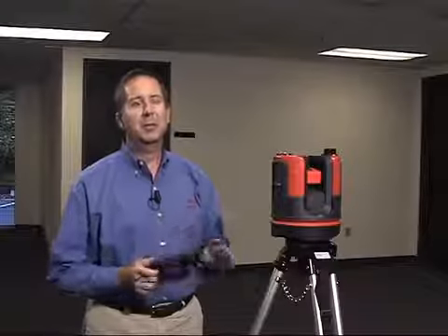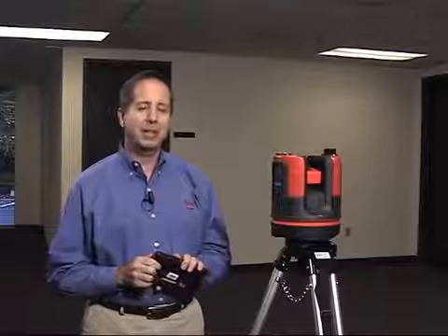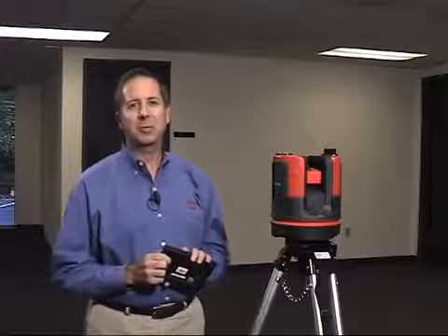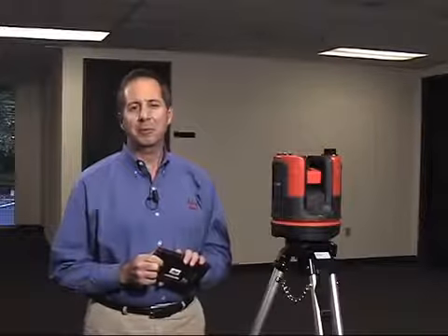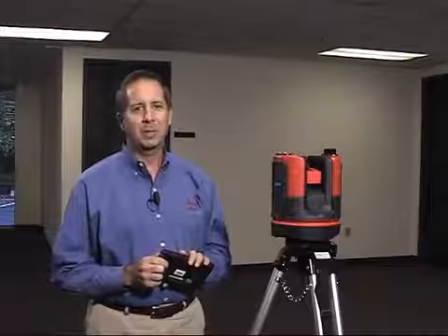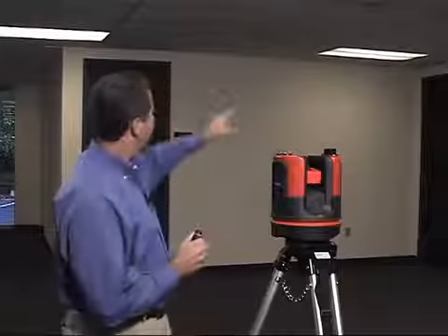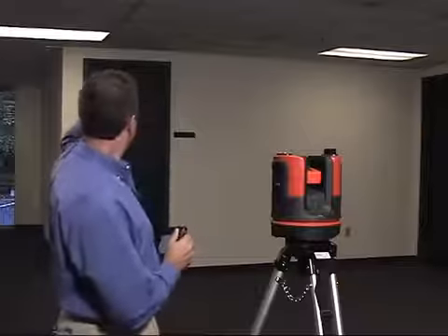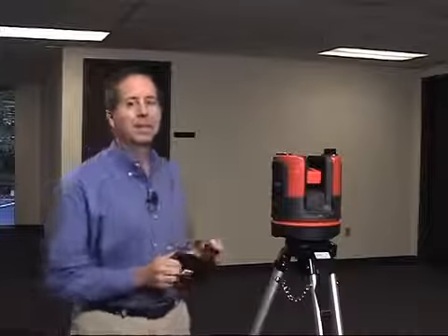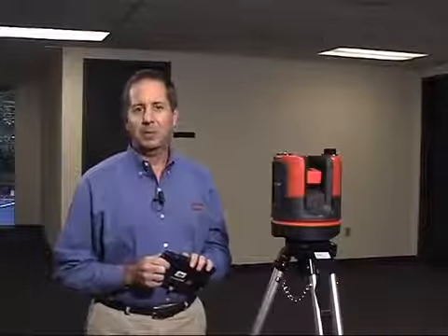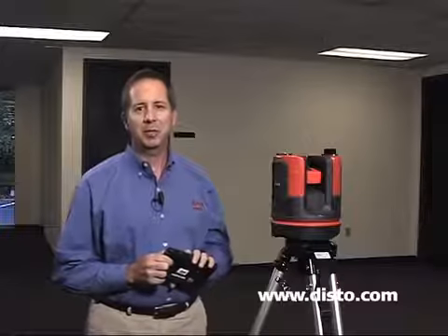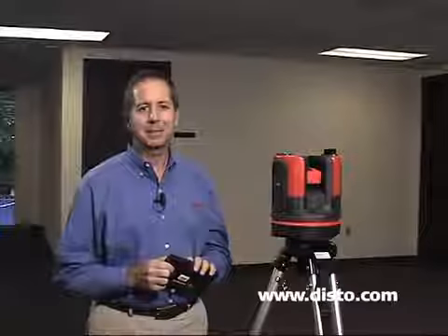As we get started here, we're first going to measure the wall plane behind me and locate the door. In order to do this process, we're going to measure the four corners, and then when we're finished with that, locate the door. First, we're going to measure the points in the corners, 1, 2, 3, and 4, and lay out that wall plane. Once we have laid out the wall plane itself, then we will locate and position the door inside that wall plane.